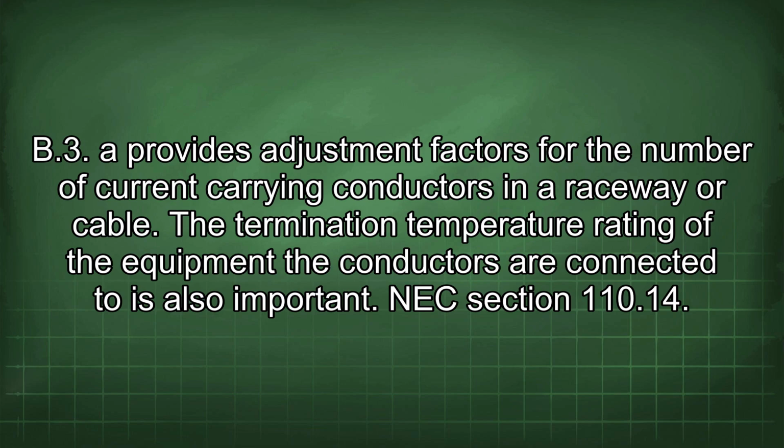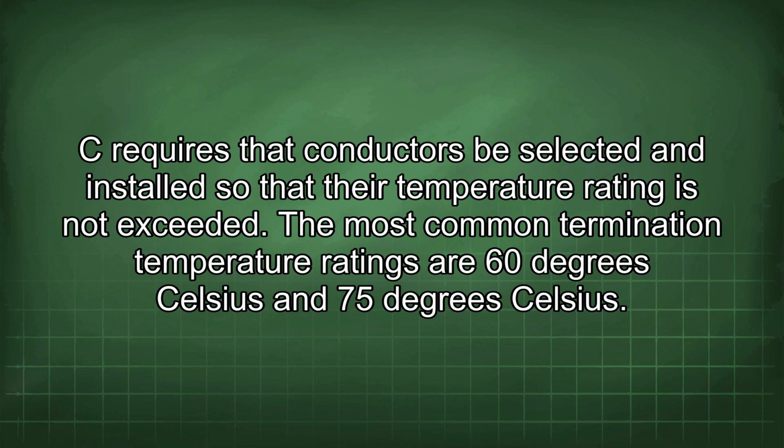The termination temperature rating of the equipment the conductors are connected to is also important. NEC Section 110.14(C) requires that conductors be selected and installed so that their temperature rating is not exceeded. The most common termination temperature ratings are 60 degrees Celsius and 75 degrees Celsius.